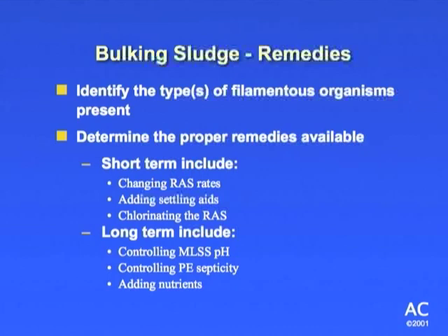Again, as we said, with the new nutrient removal processes here, you will have a better settling sludge, so you may be less susceptible to having this problem occurring, I would hope. That's one of the benefits of running a nutrient removal process, getting a much better settling sludge. The selectors just encourage it because of the food to microorganism ratio in them.